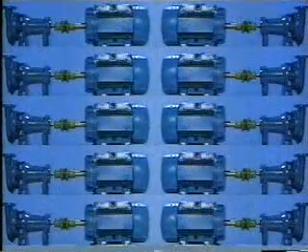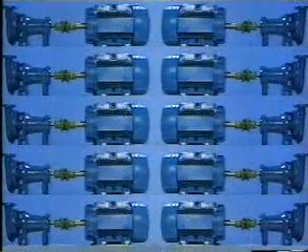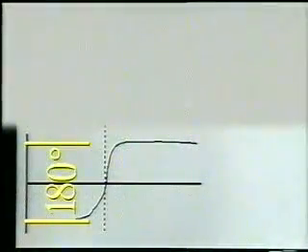A typical example is when there are several machines of the same type nearby, such as a row of identical pumps or fans. A coast down may indicate a good phase shift at a particular frequency, and we would expect a high vibration at the same frequency.